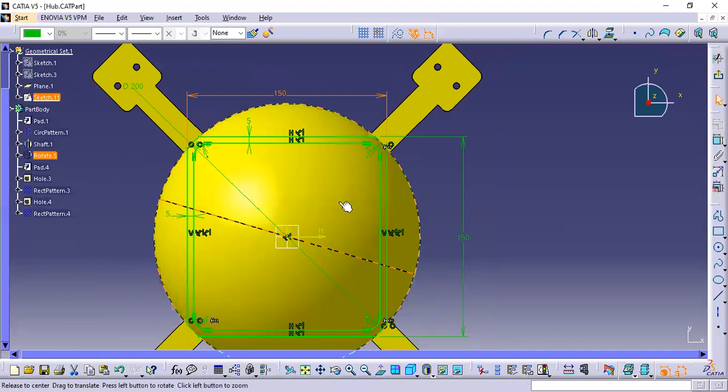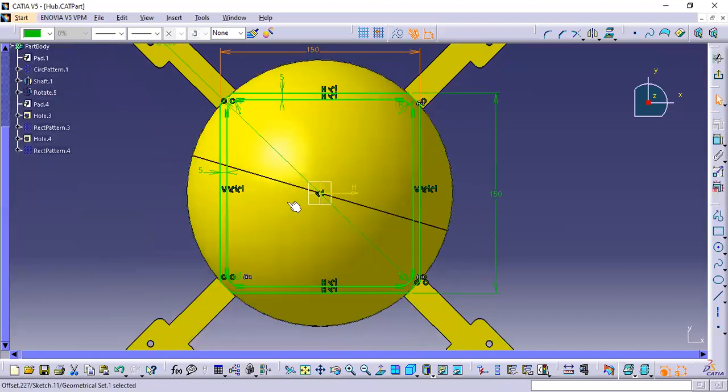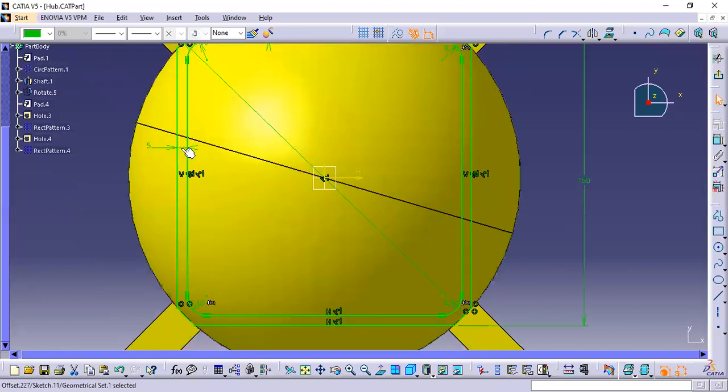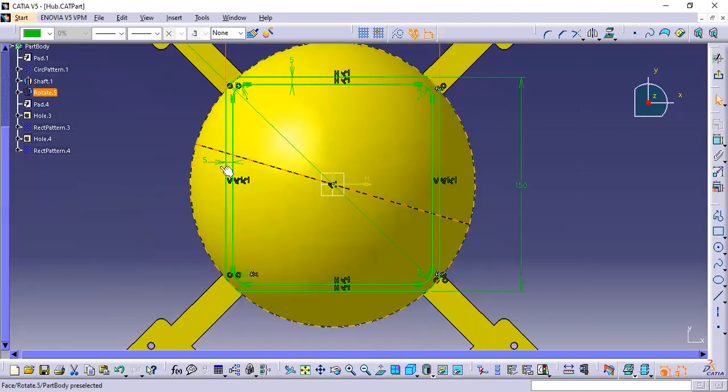And most importantly for this mounting bracket design is the thickness. So we maintain the thickness of 5 mm, which we think will be sufficient to sustain the housing, the payload compartment, as well as the landing arms.